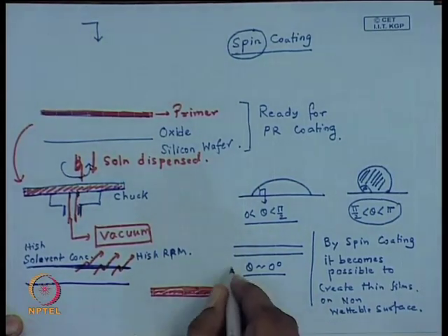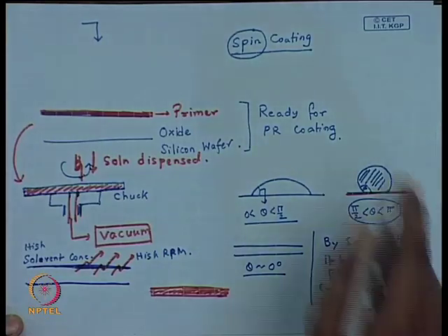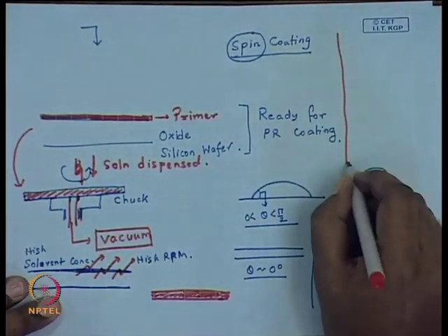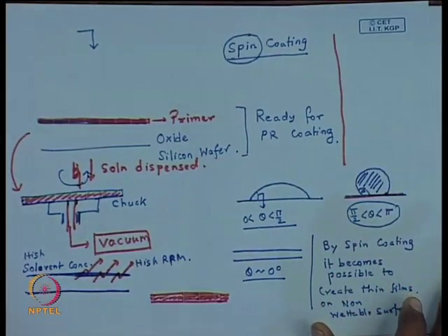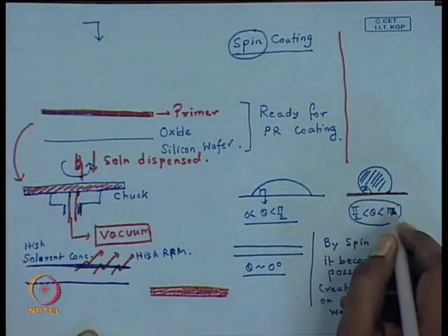Now, once you complete the process of spin coating, towards the end of the process, even if you have a non-wettable surface, you have a layer of polymer or photoresist which is deposited onto it. In case of photoresist, that is typically not the problem, but there can be various other settings or experiments where you may want to have a continuous film on a non-wettable surface, and spin coating is indeed a preferred technique. Now, this polymer layer, though thermodynamically it is unfavored, looking at the spreading coefficient, because the surface does not want to remain covered with this polymer,